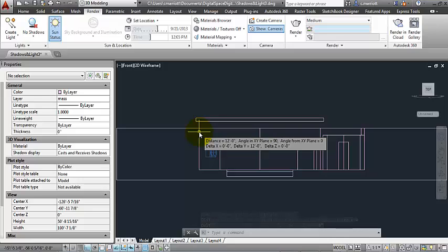And so what I'll do is I'll take that 12 feet and convert it into inches. So 12 times 12 would be 144. I've got 144 inches that I need to climb. And then the other thing that I will do is figure out how many risers I need. I'll divide that number, 144, by 7.